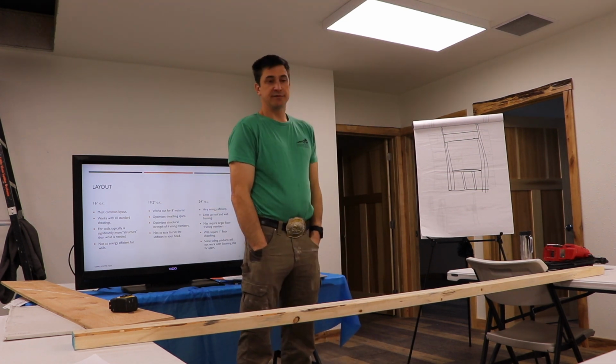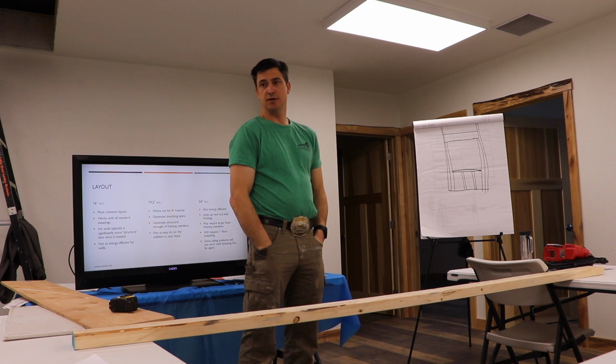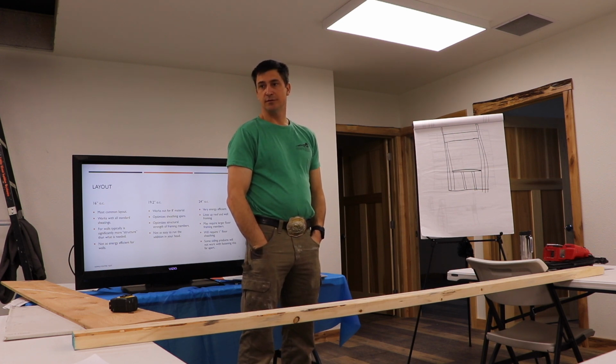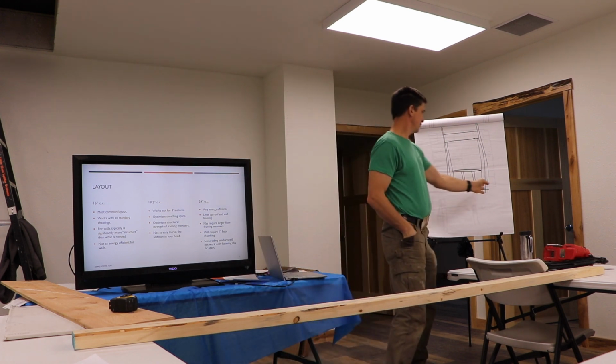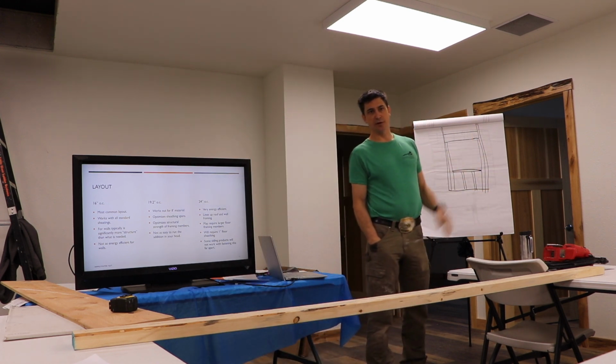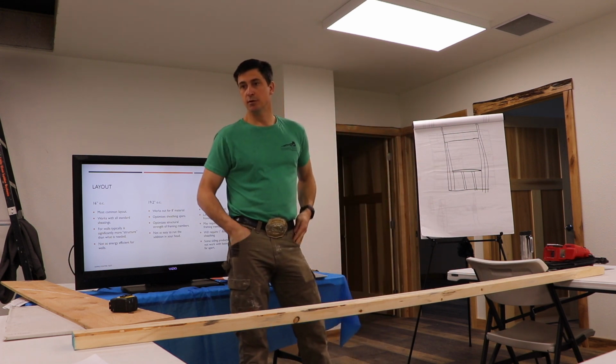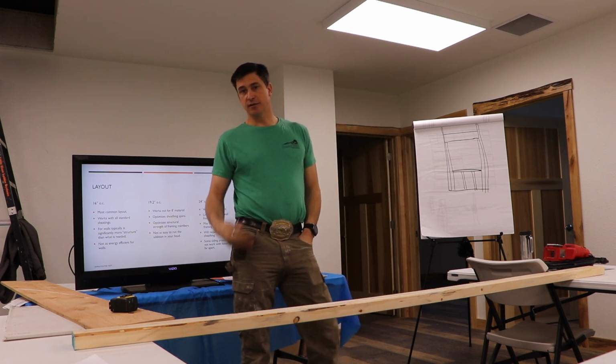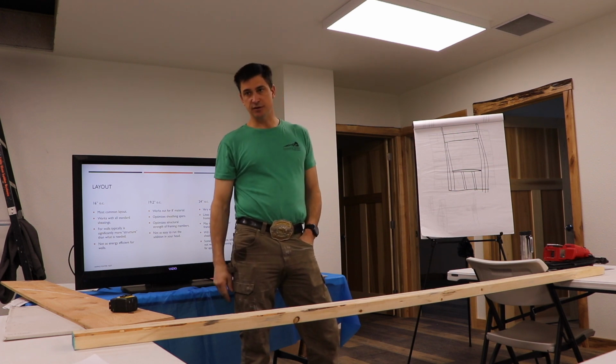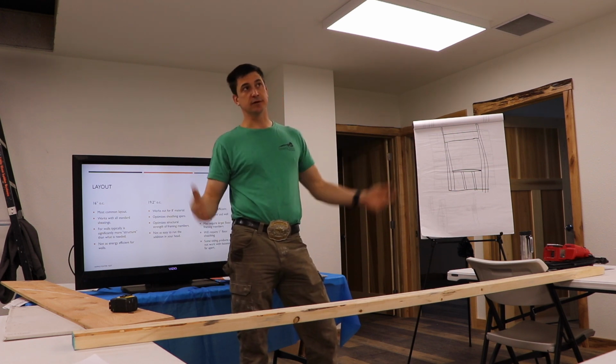And really when you have something that close and you have a door or a window, there is no compelling reason to be like, yep, layout puts one 2 inches away, we got to put it in there. I would say 100% of the time pull it out. Unless that's exactly where your sheathing layout comes out, then, well.